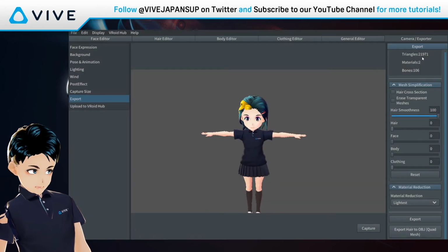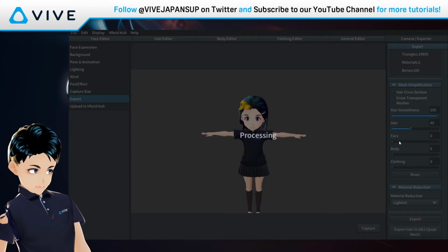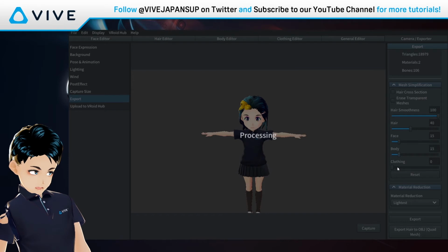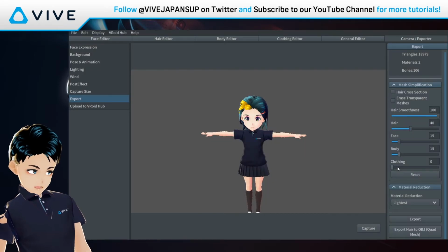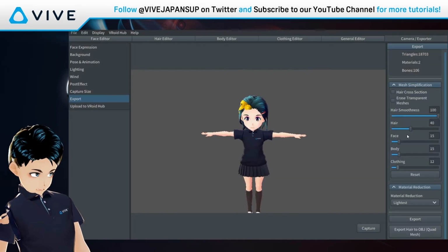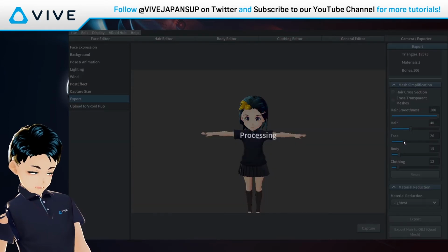So you can see that we used to have 22,000 triangles in this character. And by changing the setting, we cut almost 20 to 10% of those triangles. And it's gonna help a lot on your computer, a lot on VRChat, and also if there are a bunch of people that doesn't do this, then it gets crazy. Your computer won't be able to show all those characters.